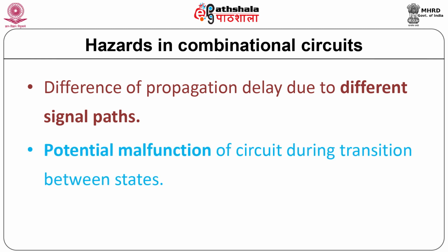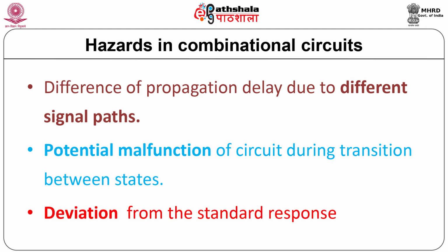The hazard can also be defined as the actual or potential malfunction of a logic circuit during transition between two input states when a single variable changes. The term malfunction means any deviation from intended or standard response. When the changes in the input signal do not change the output signal due to some form of delay caused by logic building blocks like NOT, AND, OR gates, etc., this generates a malfunctioning in the performance of the circuit.